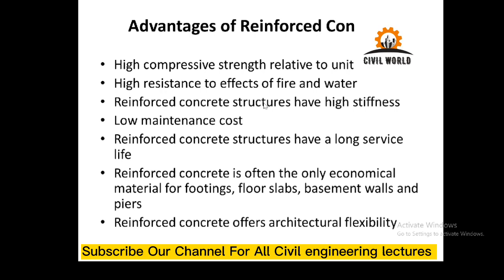Coming to advantages of reinforced concrete, they have high compressive strength relative to unit cost. So the cost per unit compressive strength is very low. They have high resistance to fire and water compared to steel construction. Reinforced concrete structures have high stiffness compared to steel, which is ductile, and thus they have low vibrations.